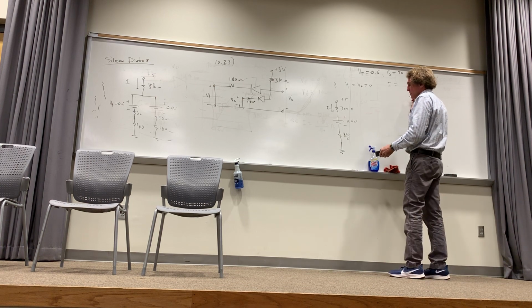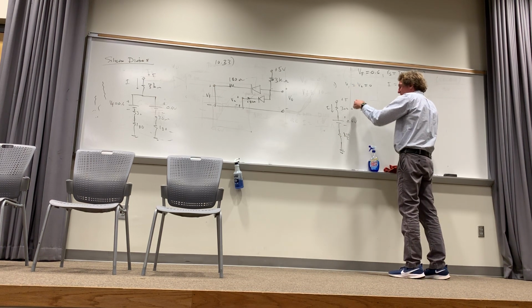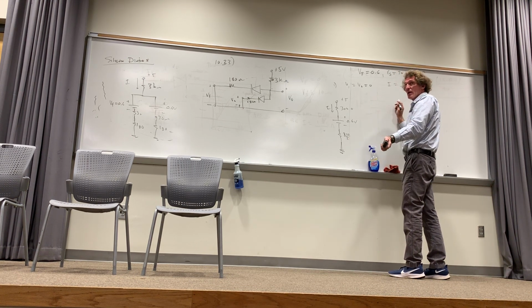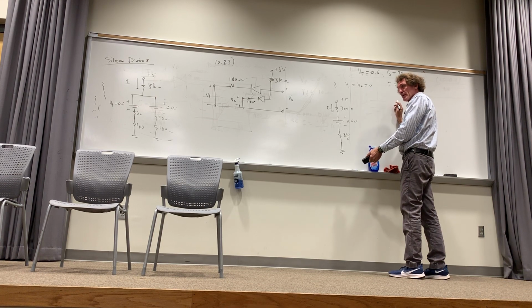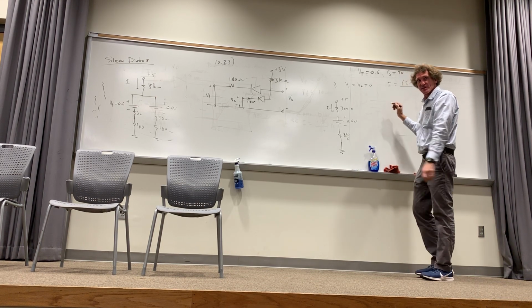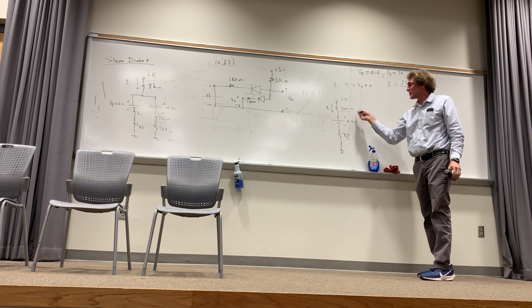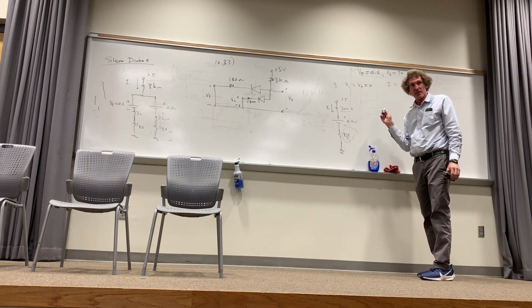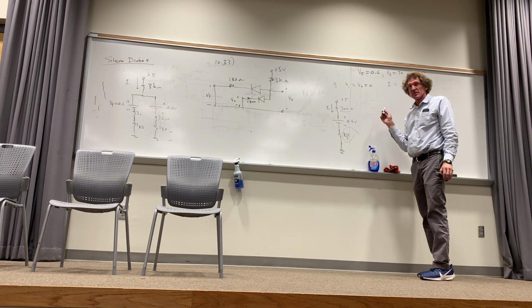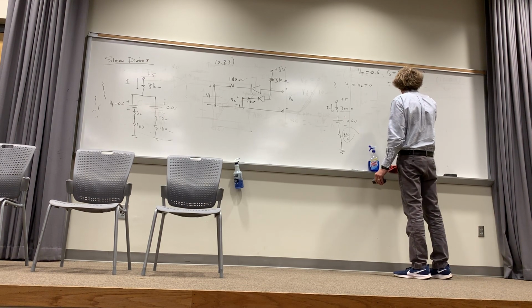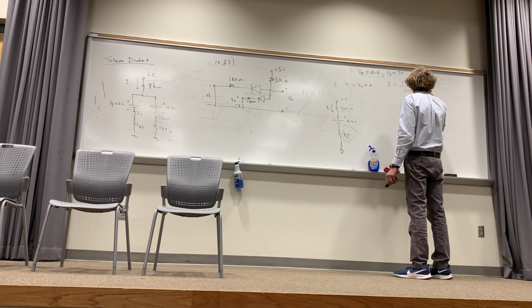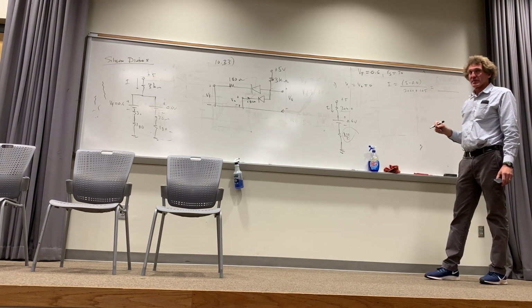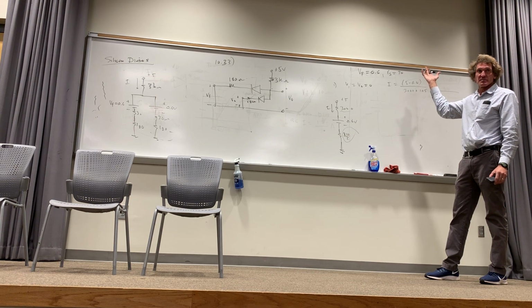What would it be? Well, now the total voltage driving current this way is 5 minus 0.6, isn't it? And what limits the current? Class? You all see it? You're usually not that shy. 3,000 at least, right? Plus what? Plus 210 by 2, right? Which is 105, isn't it, class? So I divide this by 3,000 plus 105. And that would be the current if both V1 and V2 are grounded. Does that make sense to everybody? Give me a show of hands if it does.